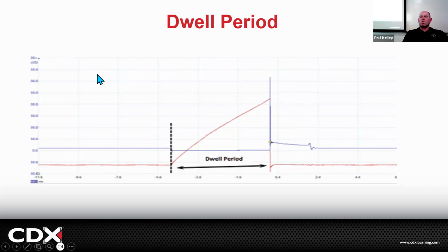Now, is the customer going to want us to spend all the time doing all these measurements? They're going to be like, AutoZone does free diagnostics, remember? I'll be like, yeah, we got to hook up the oscilloscope and check your firing line and see if it's too high. Make sense? We'll come back to that a little bit, but this waveform right here is actually monitoring the voltage, and the voltage is going to tell us a lot.